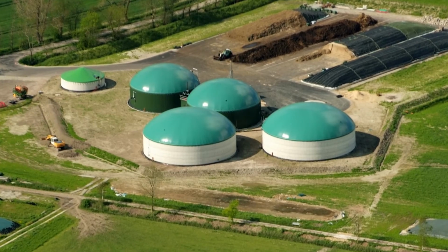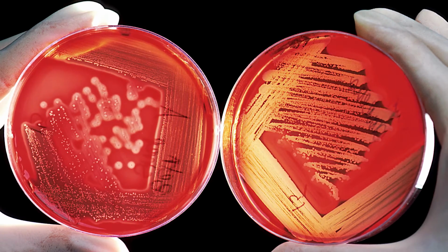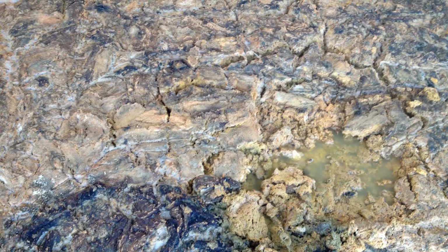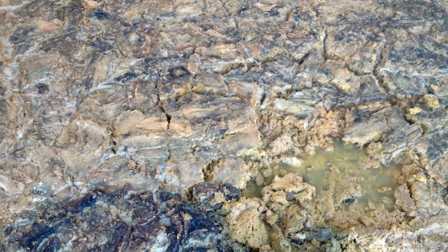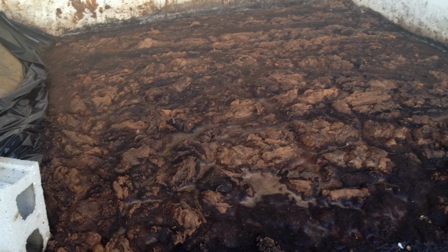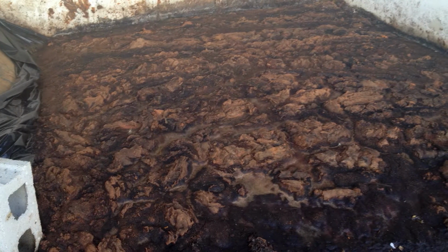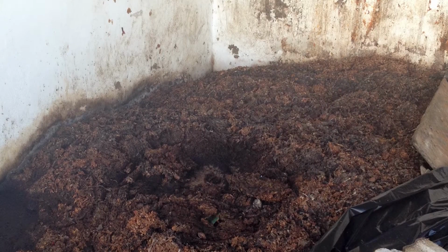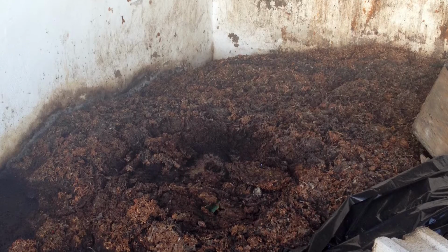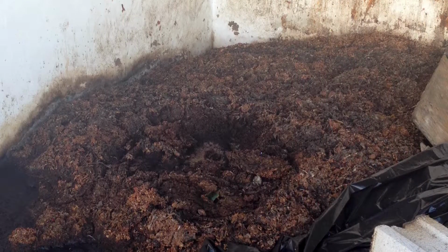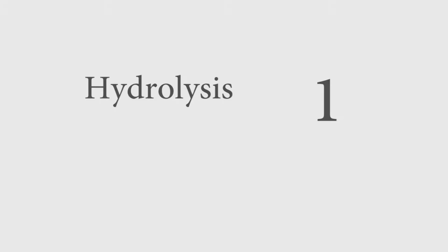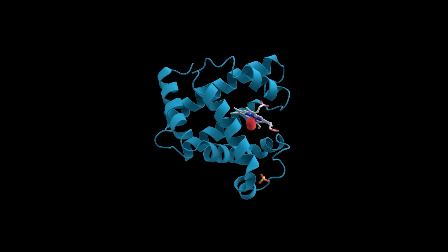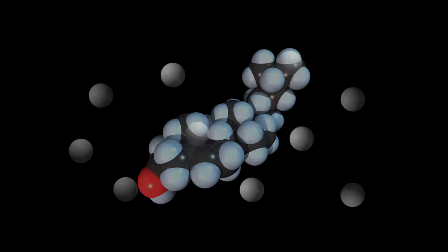Anaerobic digestion is a very complex microbiological and biochemical process due to the high number of biochemical reactions which take place, as well as the high amount of bacteria involved in these reactions. In fact, a large number of these reactions happen simultaneously. The process of degradation of the organic matter is divided into 4 stages: hydrolysis, a cleavage of particles and complex molecules, proteins, carbohydrates, and lipids into simpler compounds.